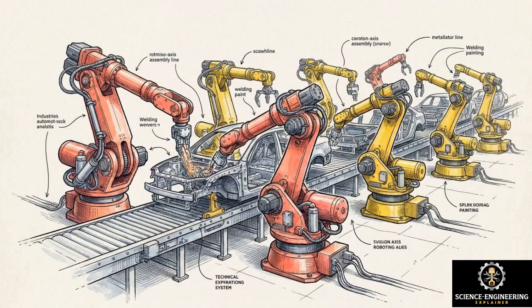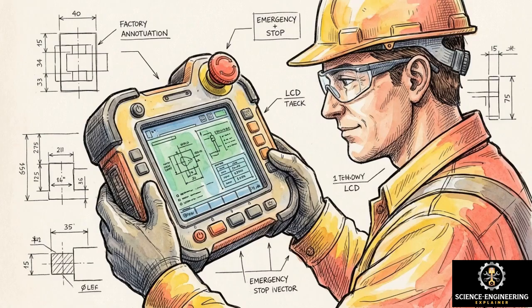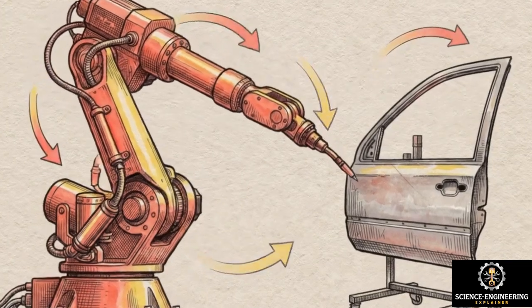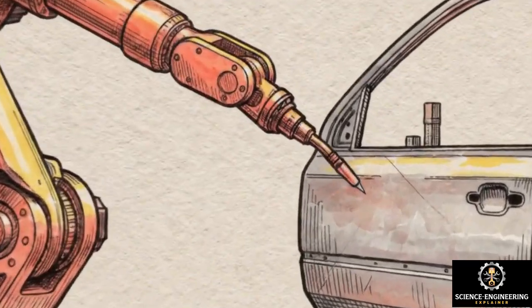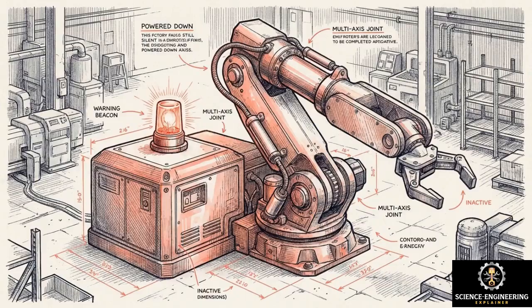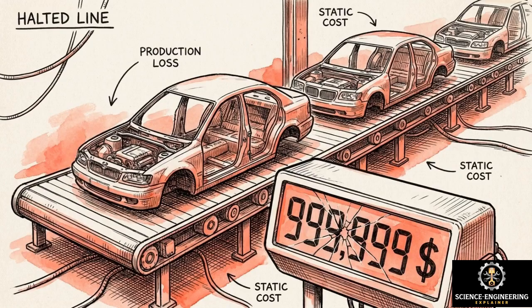If you step away from custom development and walk onto a factory floor, the rules change entirely. In industrial manufacturing, integrators often rely on online programming. Operators use handheld devices called teach pendants to physically guide the massive robotic arms from point to point, recording the exact coordinates. The drawback is that the robot must be taken offline to be programmed. In a factory, halting the assembly line to teach a robot a new path means hemorrhaging money through downtime.